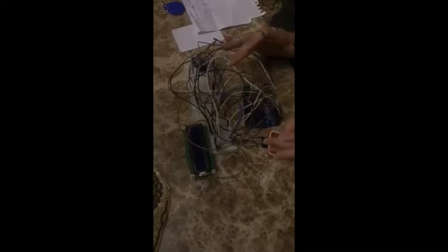It's an analog pin. Now, the LEDs are connected the same, except that they are connected to pins A0 and A1. Those pins, first we had a problem because we were using Arduino Uno. We needed more pins to use, so we changed from analog pins to digital pins. We did that for the two LEDs and the NFC and the smoke sensor, as well as to the LCD.